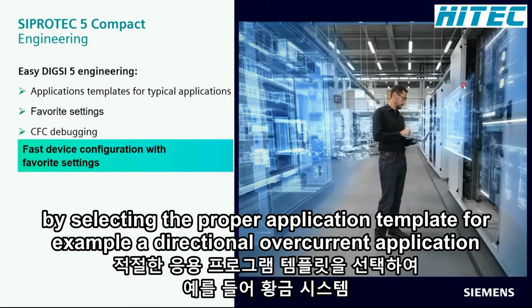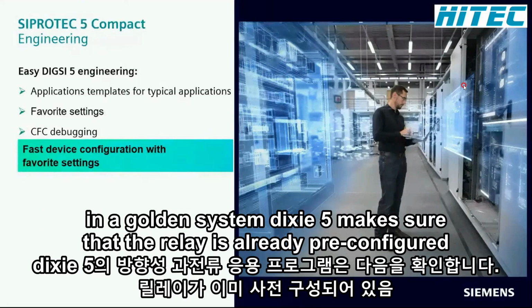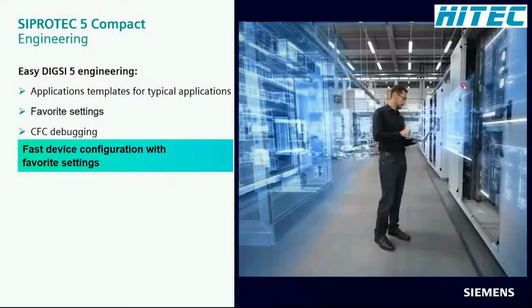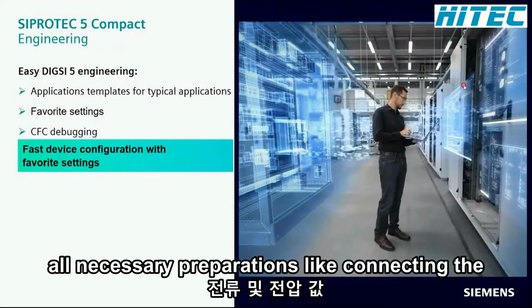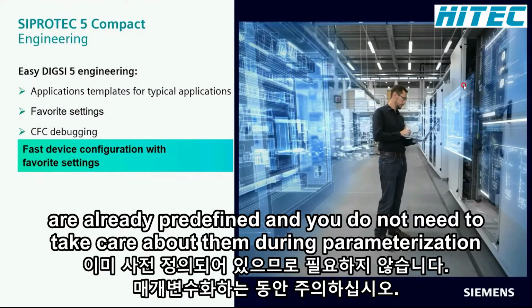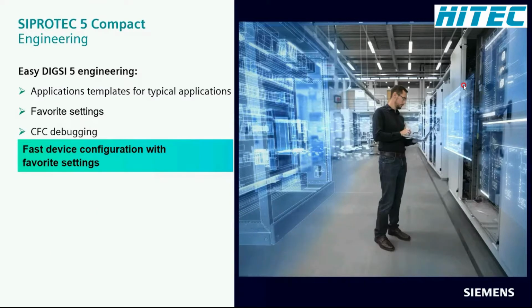By selecting the proper application template, for example, a directional overcurrent application in a grounded system, DIGSI 5 makes sure that the relay is already pre-configured with the necessary functions and routings. All necessary preparations, like connecting the current and voltage values to the protection functions, are already predefined, and you do not need to take care of them during parameterization.